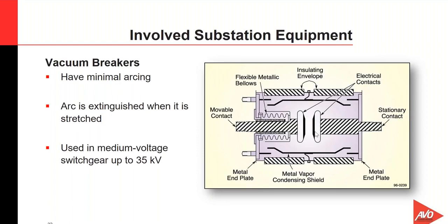All right, so our SF6 type breaker, sulfur hexafluoride type breakers, uses gas to extinguish the arc internally. This type of breaker has excellent dielectric and arc quenching capabilities. All right, it's easy to maintain. As far as it being compared to the oil or air, it is superior because of its long life. It's a simple construction, easy to maintain. Contacts open and close internally, and SF6 helps to extinguish that arc, helps to minimize that arc internally.